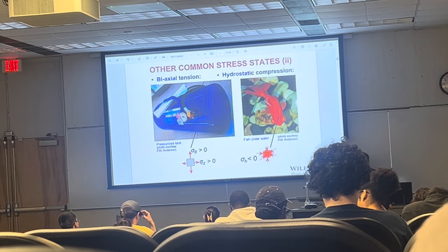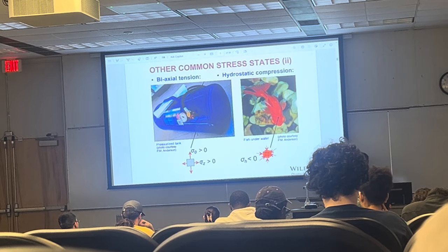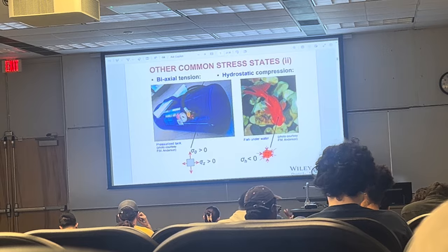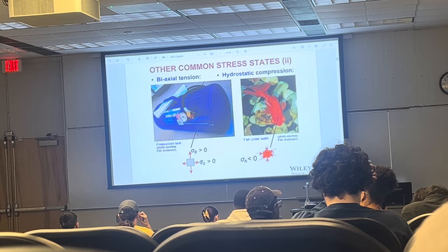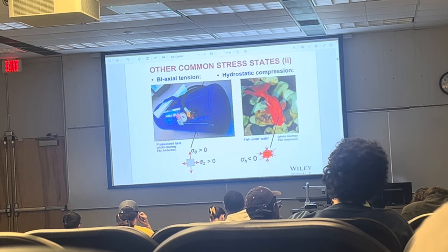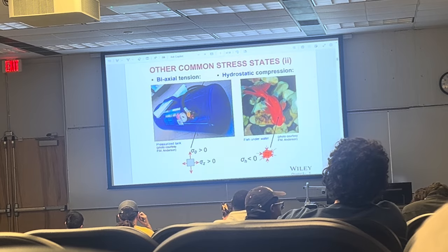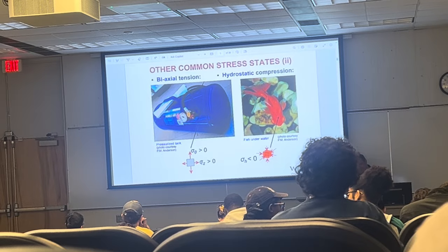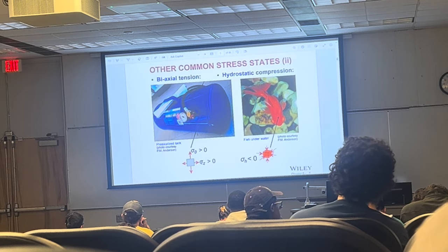But if it's out of plane stress, what is it going to be equal to? If it is an internally pressurized cylinder, it's going to be equal to the pressure inside. And the reason we ignore it is because those two stresses are at least 10 times higher. So we just ignore that one.